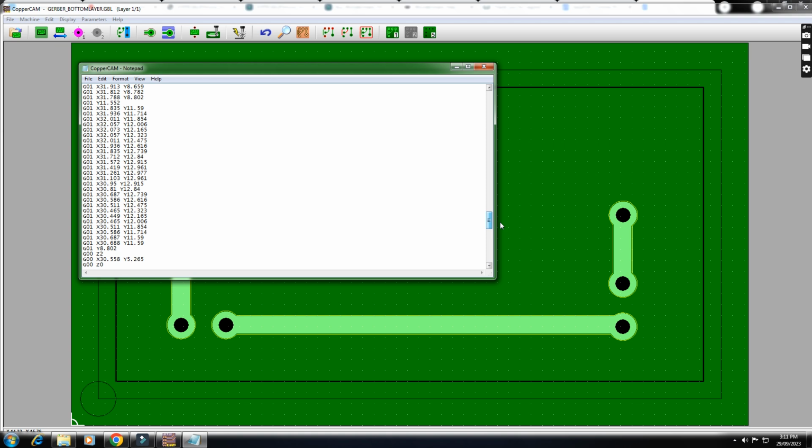In the Gcode, at the end, once this operation is completed, the tool has to reach the home origin. It should go back to the origin. For that, you have to add codes manually. The command is G00 X00 Y00, so that it will be back to the origin.